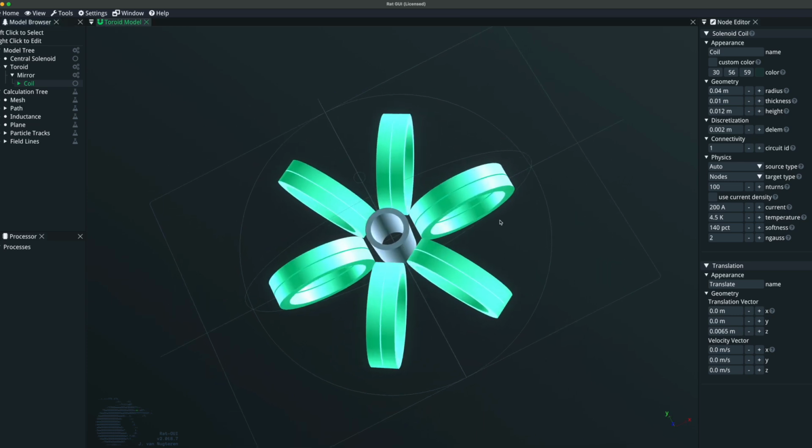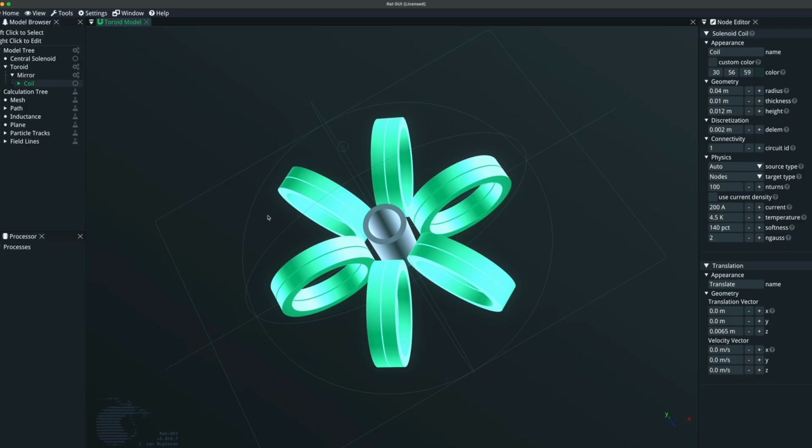Now, peak field is important when you are using superconductors, because basically the peak field determines your margins, your temperature margin, your load line fraction, and so on. So if you're really designing on the edge of your margins, you really want to have a very accurate peak field, and that's one of the reasons why you could play with these settings here.